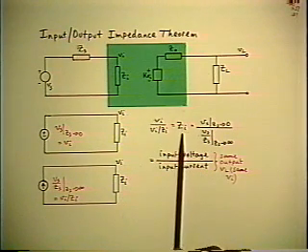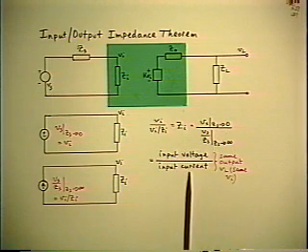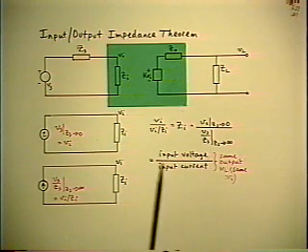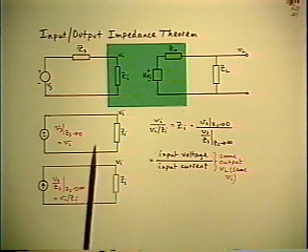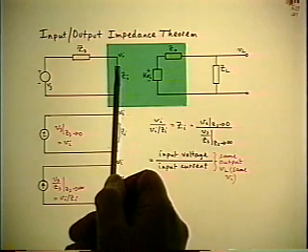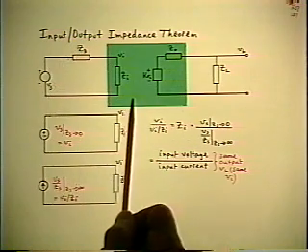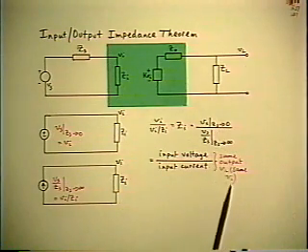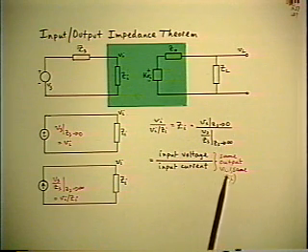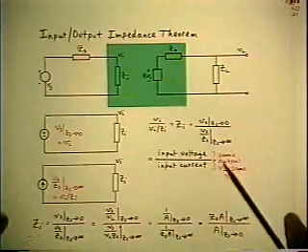and you're left with Zi is equal to the input voltage divided by the input current that gives the same value of Vi. Again, the same Vi is a necessary condition, otherwise it doesn't cancel out. But if you have the same Vi at the front end of the amplifier, regardless of whether you've driven it from a voltage or a current, then of course you get the same output voltage as well. So you do the same trick. You divide the same output voltage into both numerator and denominator of that expression.